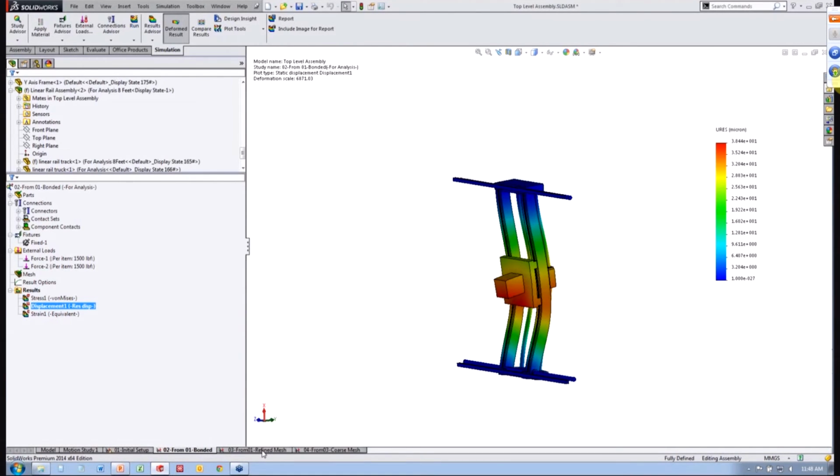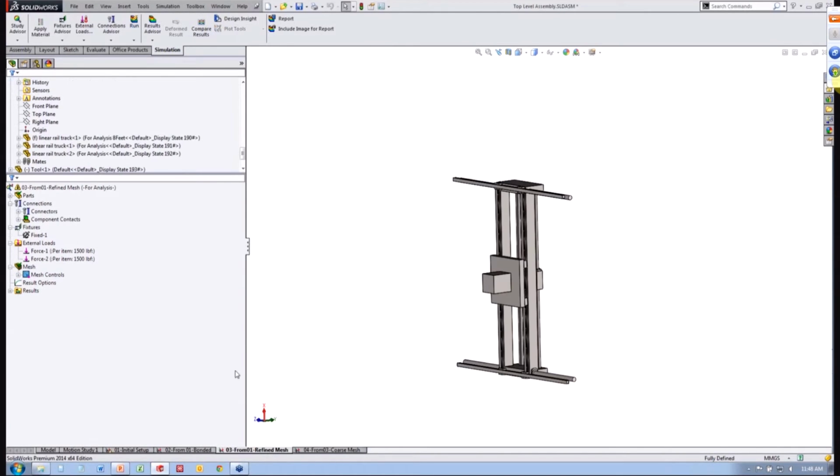So I'm not going to show the actual results, but I'll describe what we did to obtain an appropriate mesh for this analysis. We had a larger assembly than what I'm showing here, but what we wanted to achieve with the mesh was 2 elements across the thickness in the areas of influence.